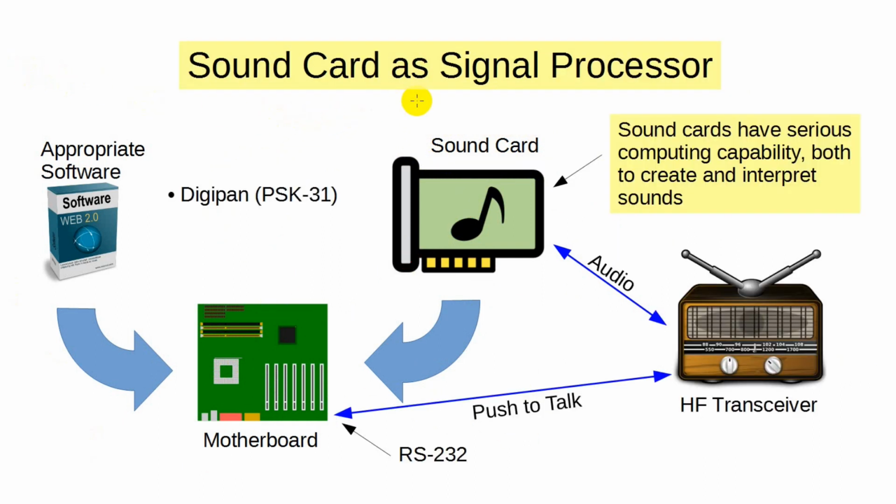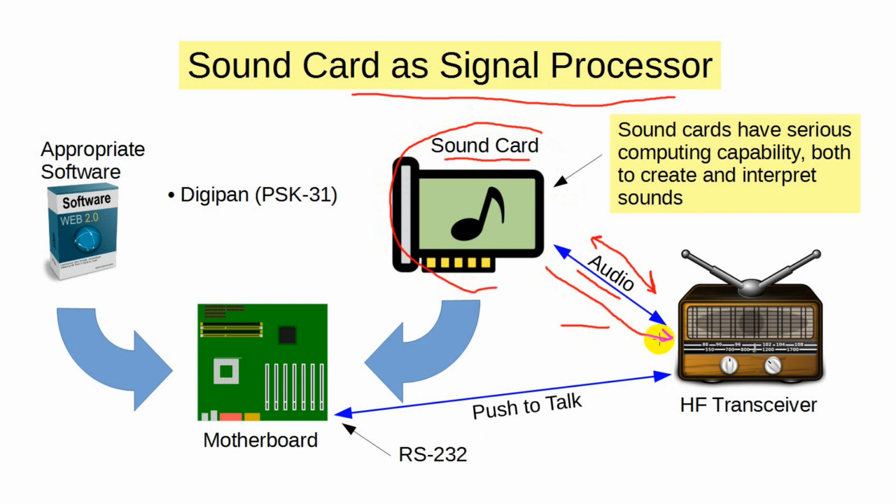It didn't take long for hams to figure out that if a sound card could create music, it could certainly create the audio tones needed for packet and AFSK. In other words, you could skip the PK232 and its competitors and just connect the sound card's audio input and output to the transceiver. A separate path was needed to key the transceiver, that is, tell it when to transmit and receive.